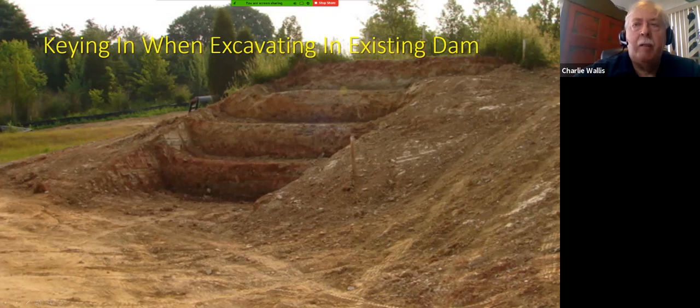Sometimes it's necessary to do an excavation in an existing dam, and rather than do a straight trench, it's desired to cut back into the dam further and to key in the excavation so that when you replace the soils, you're able to bind it into the existing dam in a better way rather than having one smooth surface for failure.